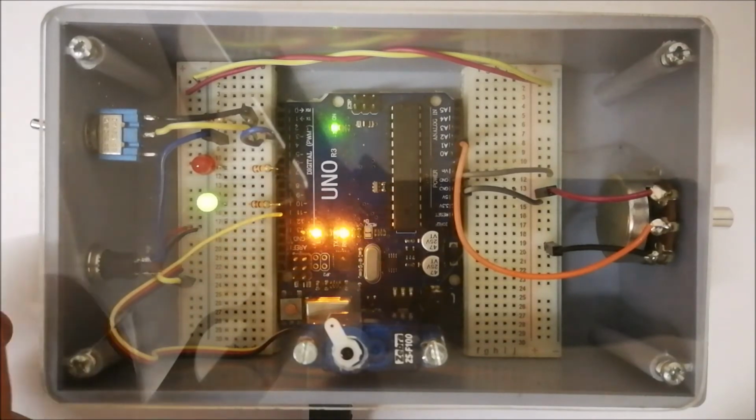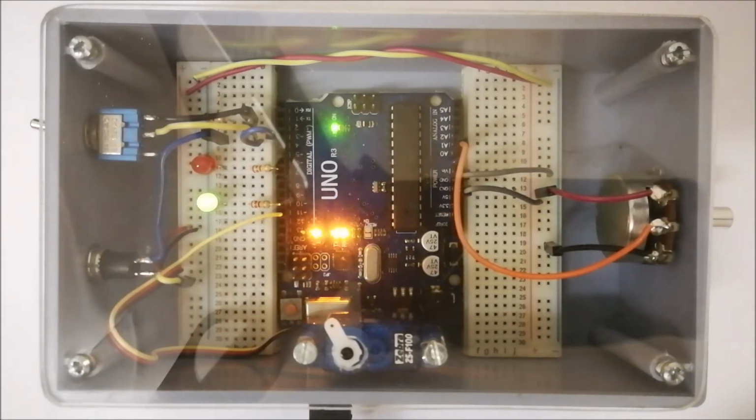So what I've done now is I've deactivated this pull down resistor and I've switched the switch across. Now what you'll see happening is every time I push this button, the red LED is flashing on and off. The reason for that is that there's now some charge connected to this input pin from this push button, and it's fluctuating. The microcontroller doesn't know if it's a 1 or a 0, and so because of this fluctuation, it doesn't know should it output a 1 or a 0. Eventually the charge builds up and it goes on.